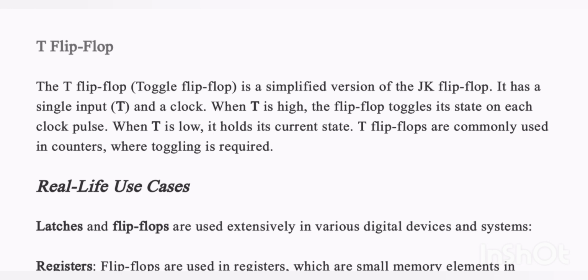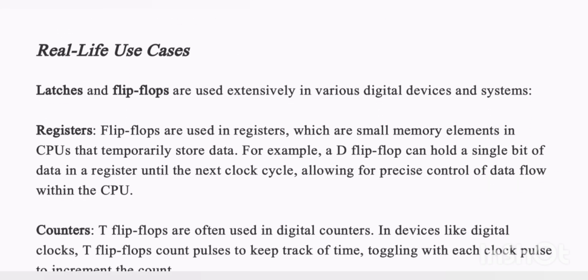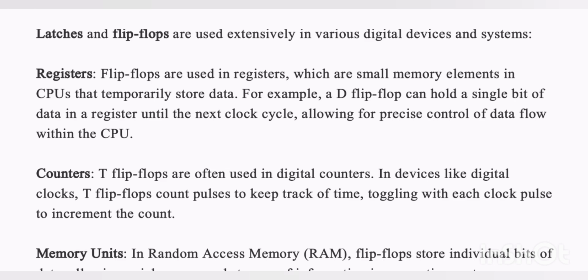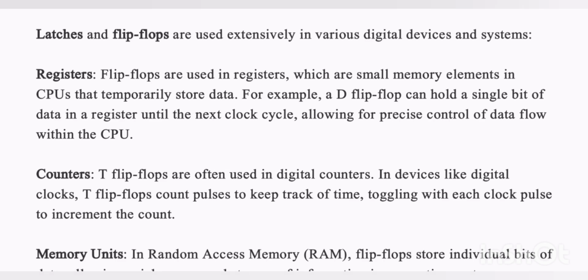Real-life use cases. Latches and flip-flops are used extensively in various digital devices and systems. Registers. Flip-flops are used in registers, which are small memory elements in CPUs that temporarily store data. For example, a D flip-flop can hold a single bit of data in a register until the next clock cycle, allowing for precise control of data flow within the CPU.